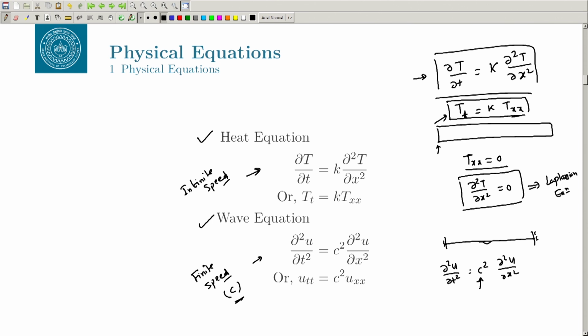On the other hand, if I am speaking here, I am speaking to you, the sound is travelling at a constant speed, which is the speed of sound, which can be determined based on the room temperature, and we have talked about this c equal to square root of gamma R T for the isentropic process, which is fairly valid because we are not adding heat when we are speaking.